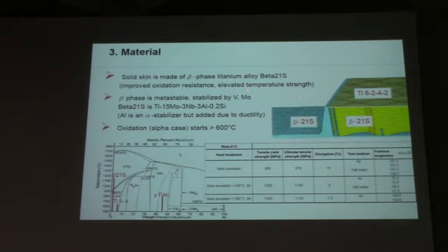It is an alloy made of titanium. Although it is the aircraft structure, it's not the one that we are used to, not a structural component. Actually, this one is so-called Beta 21S. This is a special alloy with the beta phase of titanium. As some of you probably know, it is metastable.